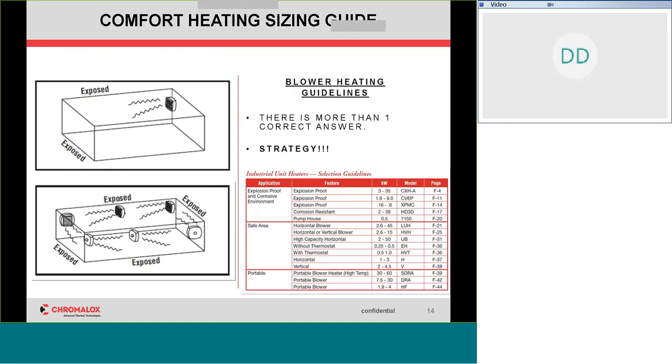Then I mentioned before, the strategy. We're applying heat to a room. It's going to provide heat to the room. It's important to remember that. We can show you where the math comes from. We can show you about insulation losses. We can calculate for unknowns and for extreme cases. More importantly, what is the customer interested in? Maybe the limitation is, I've only got a 20 amp breaker to run this off, or a 50 amp breaker. Okay, well, let's start there and let's spread the heat out. This becomes you educating your customer.